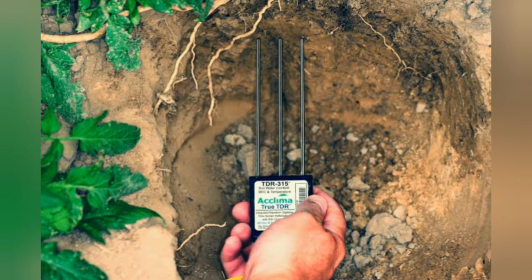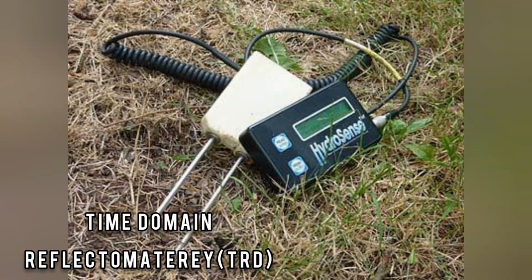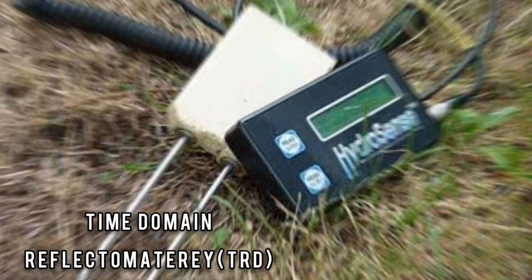The third type is time domain reflectometry. It is the most costly tool for soil water monitoring. It is portable and quick. Some units require calibration and may be finicky to work with. Accuracy may be reduced on soil heavier than a clay loam.